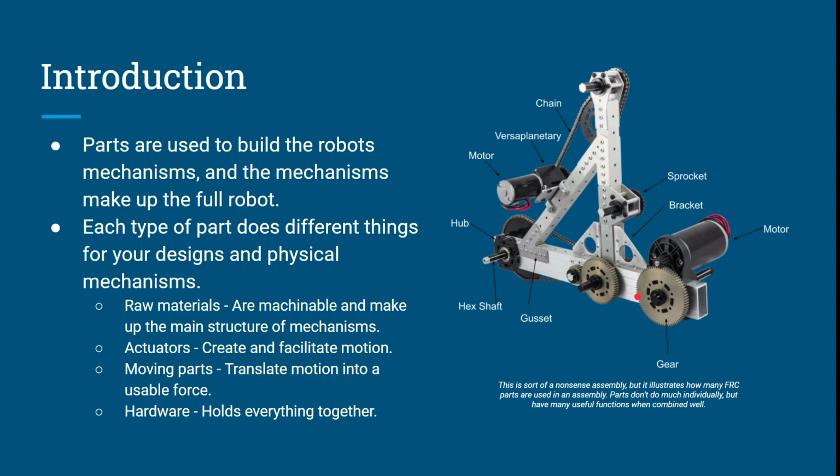So you have your gear, which is a moving part. You have this pinion gear on this motor, which connects to this gear, which connects to this shaft, and a shaft is another type of moving part. We typically use hex-shaped shafts, so hexagonal. That's because they grip onto stuff well. They don't really want to rotate inside a hexagonal shaped hole because there's a lot of surface area in contact, and there's also angles.